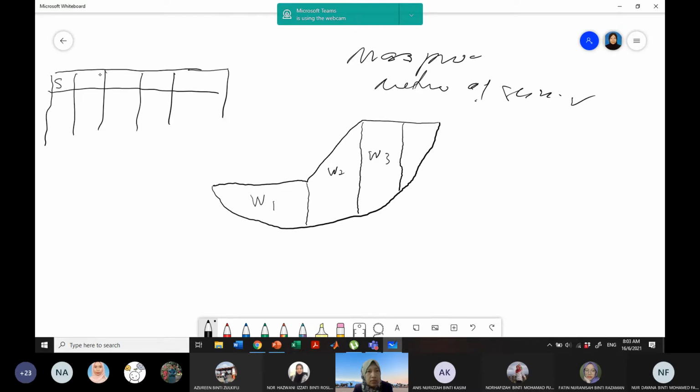So we have the slice number, we have B, the width of slice, we have H1, we have H2, we have the area, and we have the W, and then next one is we have alpha, we have T, and we have also N. T and N are interslice components that are derived from the W. The T is equal to W sine alpha, and N is W cos alpha. So T is the disturbing force, N is the restoring force.